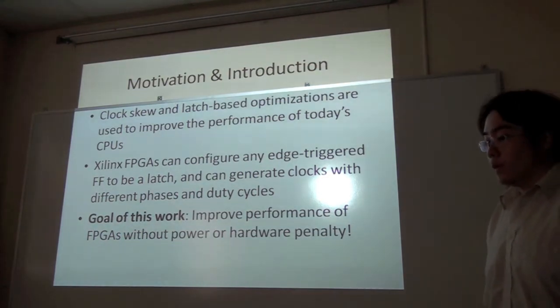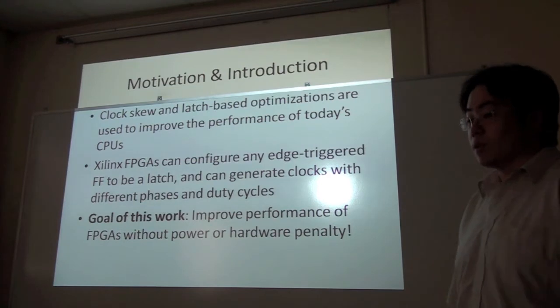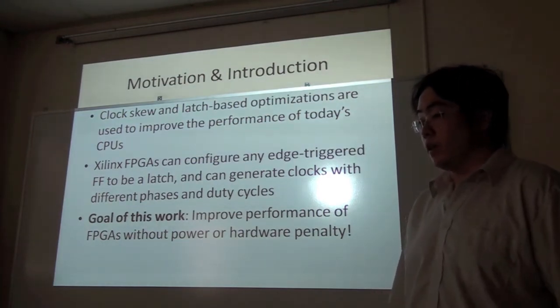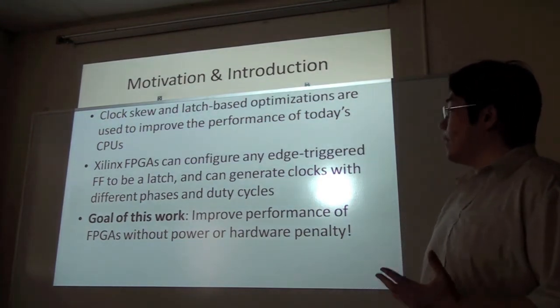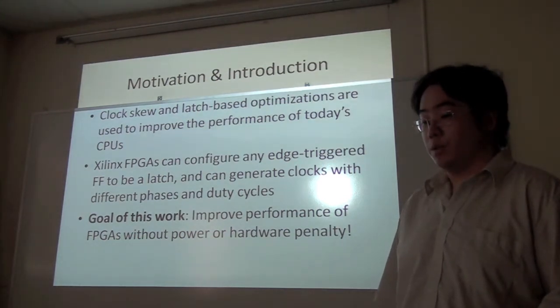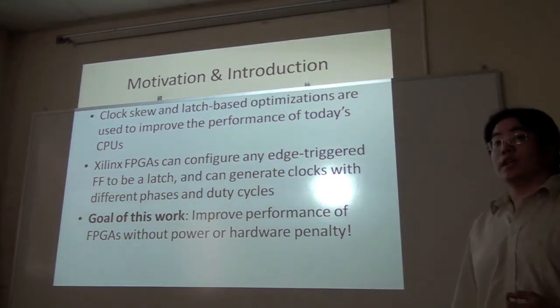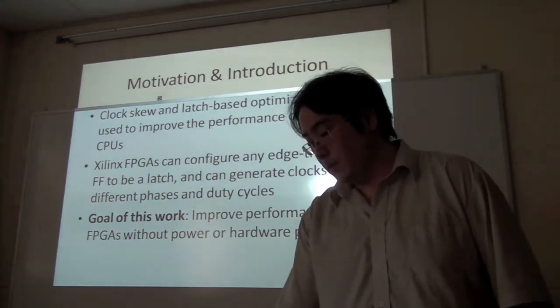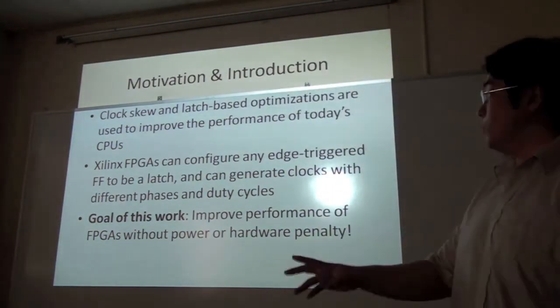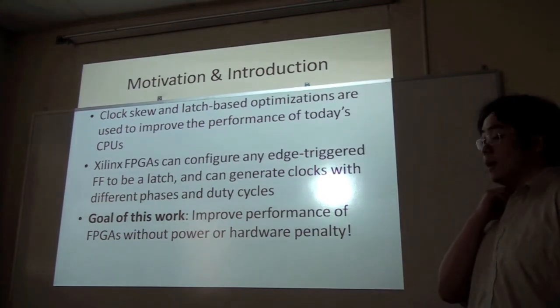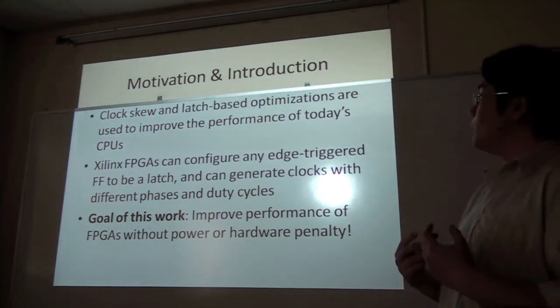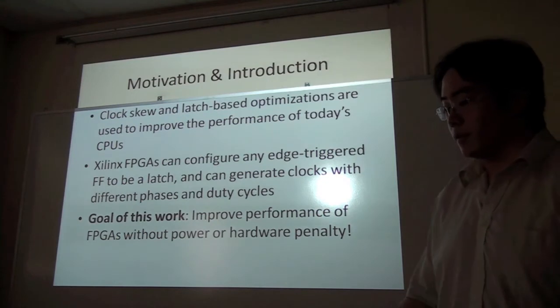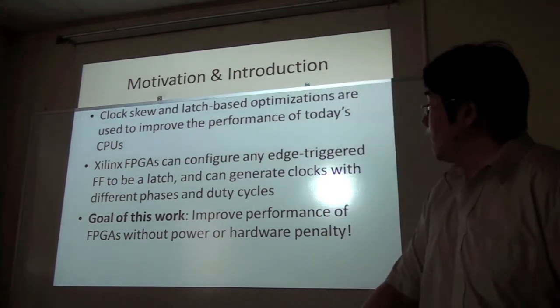What also helps is that commercial FPGAs, such as Xilinx, already allow us to configure any edge-triggered flip-flop to be a latch. And also, we can generate clocks with different duty cycles and different phases. I'll go into detail about both of these points a bit later on. But the goal of the work is to improve the performance of current designs without a power or a hardware penalty.